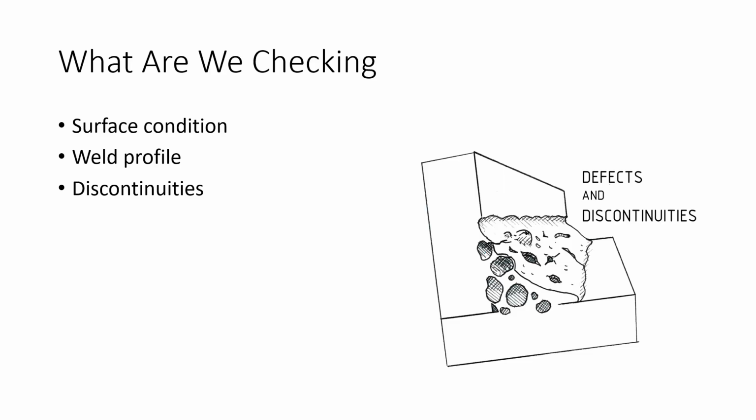And this is the basics here, but if you're getting into welding, we have terms like discontinuity, flaw, and defect. Everything that's a discontinuity is not necessarily a defect. A discontinuity is just something that is not perfect. It's not how the rest of it is, but it doesn't mean it's bad enough that we have to reject the weld and or the base material. It's just something a little different. If it's bad enough, we might have to reject it, and that would be a defect.